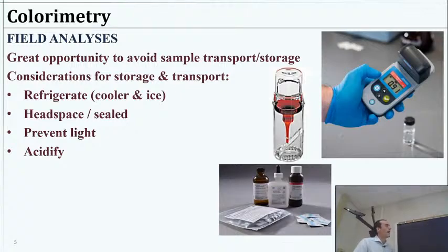All right, so then as we're doing our field analysis, there's a few other things to consider. Can we do the measurement right away in the field? If so, fantastic. If not, we probably want to put our sample on ice. Generally, we want to stop the reaction, stop bacteria from growing or dying. If we take a sample in Nicaragua on a hot day, it's pretty warm, that's conducive to reactions and bacterial growth and bacterial decay. All of that happens faster in warm temperatures. So we just chill it out, cool it off if possible, and go from there, right?